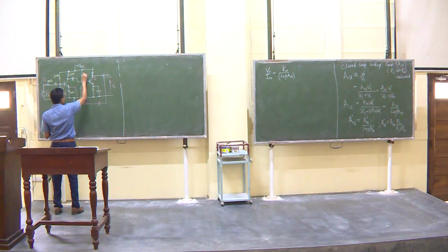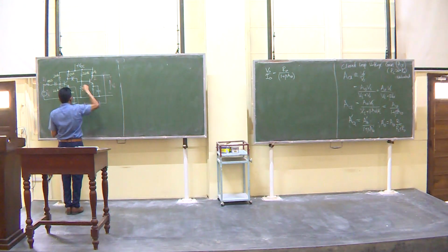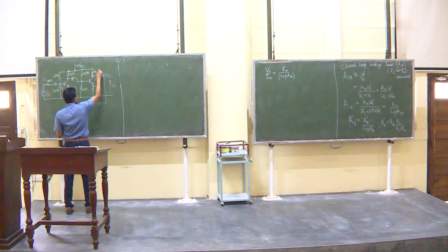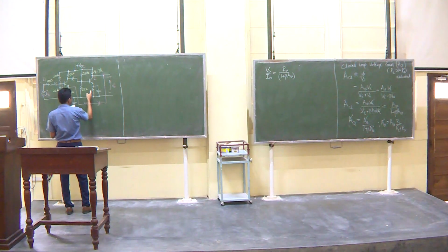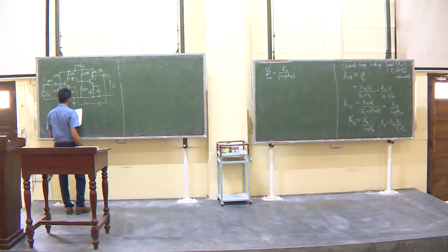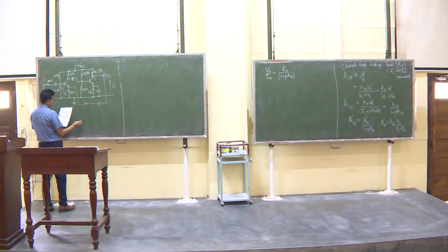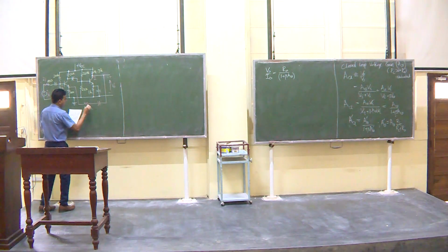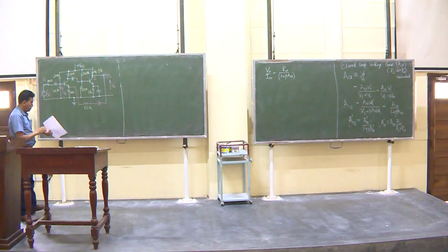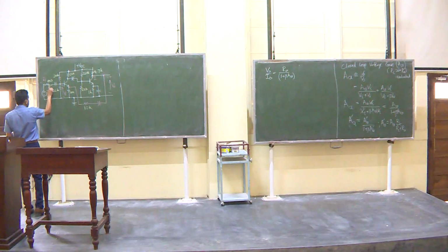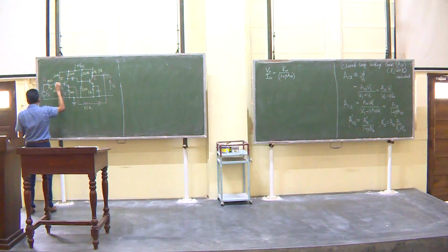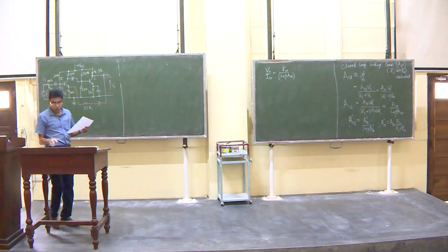This is 220 kilo ohms, that is the second stage biasing. This is again 22 kilo ohms. RC for the second stage is 4.7 kilo ohms. This is 1 kilo ohm. And this feedback resistor is 10K. Okay, so if you want, you can call this RS. I don't know if I have used any.